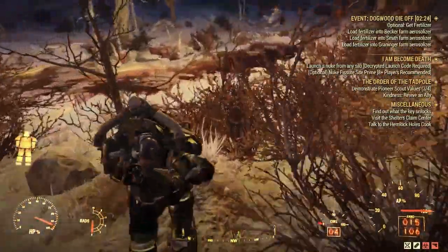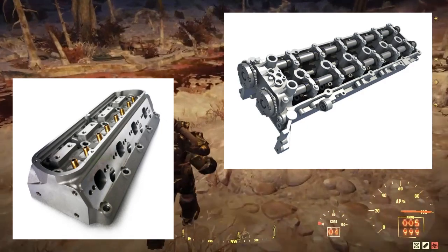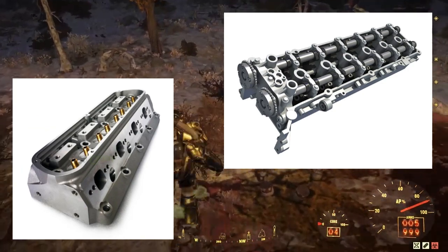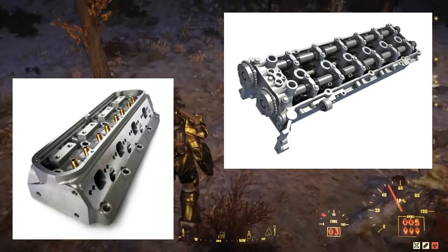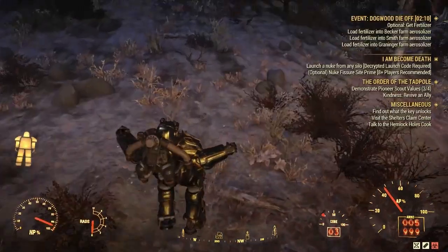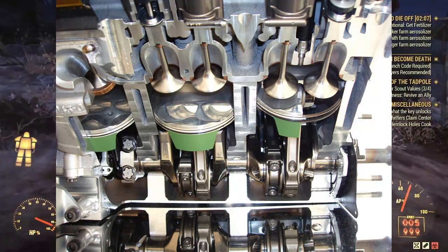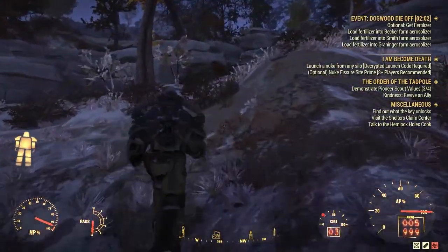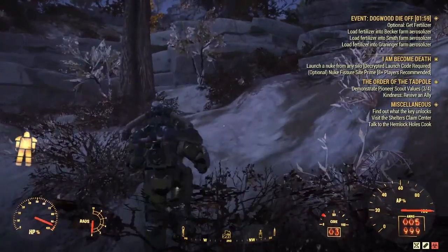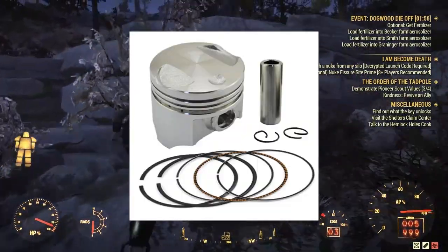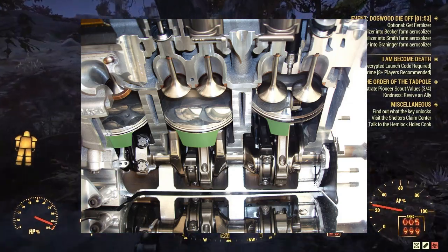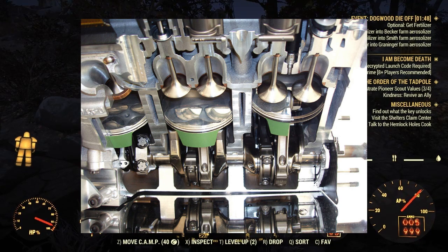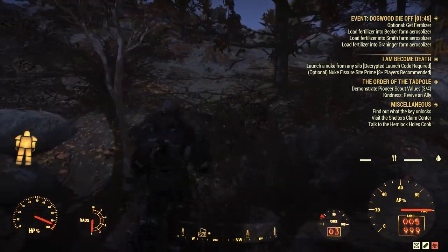Having that said, next are the heads, or as they should be called, cylinder heads. These cylinder heads create the rest of what is known as a combustion chamber. The combustion chamber is made up of three parts: the engine block that I just discussed, the cylinder heads that I'm talking about right now, and the part that I will be talking about in a bit, the pistons. Those three components make up a cylinder, a small little chamber where the controlled explosion of air and gasoline occurs.